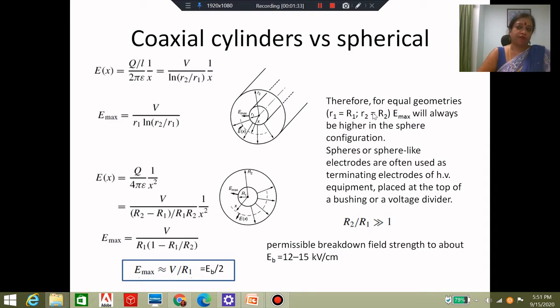And therefore, we are now looking at gas insulated transmission lines. We will talk about gas insulated transmission lines later in this course. Right now, let us just consider what these gas insulated transmission lines or gas insulated substations are. Here we are going to use pressurized gas instead of air as insulator. This pressurized gas could be nitrogen, could be SF6, could be mixtures of nitrogen and other inert gases, etc. And very often they are not at atmospheric pressure, they're at higher pressure.